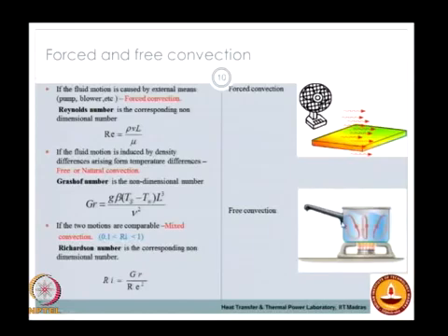Typically you can look at free convection when you boil a liquid. You do not boil it too much; during the initial stages of boiling, when you apply lower heat fluxes, you can find convection currents rising from the heated surface at the bottom upwards towards the cold surface outside. These are small currents which are set up and which can improve the heat transport.